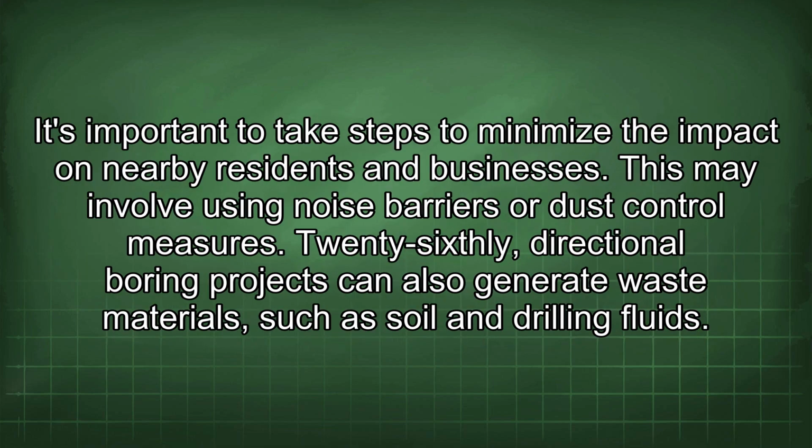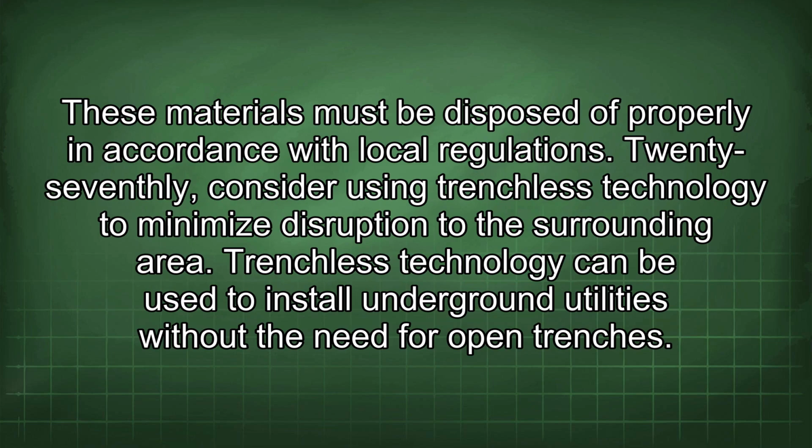It's important to take steps to minimize the impact on nearby residents and businesses. This may involve using noise barriers or dust control measures. Twenty-sixth, directional boring projects can also generate waste materials such as soil and drilling fluids. These materials must be disposed of properly in accordance with local regulations.